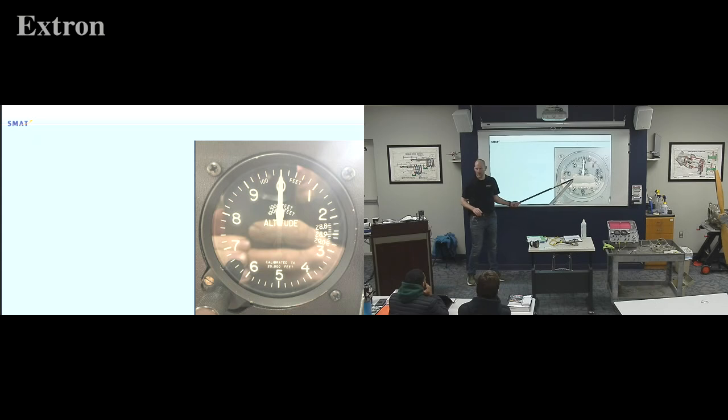This doesn't show up in many prep questions or FAA questions, but I explain this one to you so that when you call the AWOS or get the reading, you know they are not giving you what the actual pressure is. They're giving you what you would have to set in the Kollsman window for your altitude to indicate true altitude. Everybody tracking with me on that? Alright, so that's a fun little trick you can do sometime. Set it to 0 and see what pressure you're at.